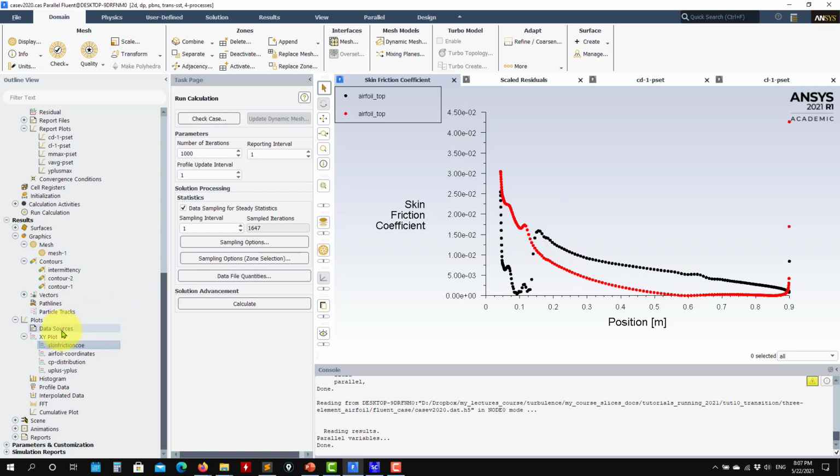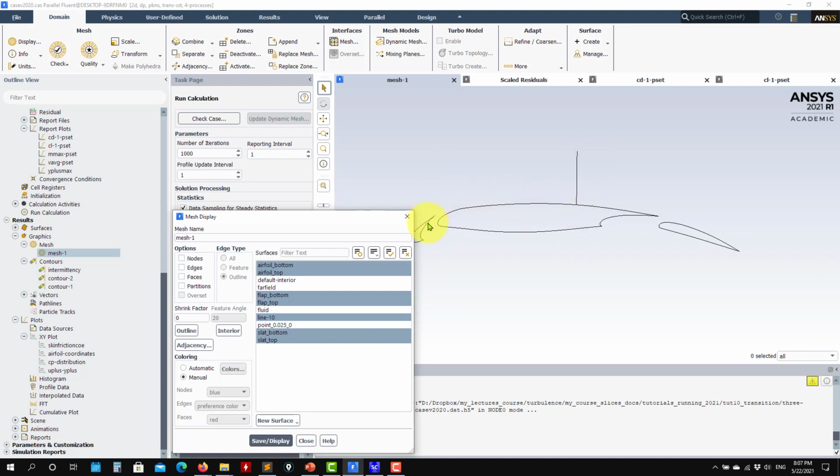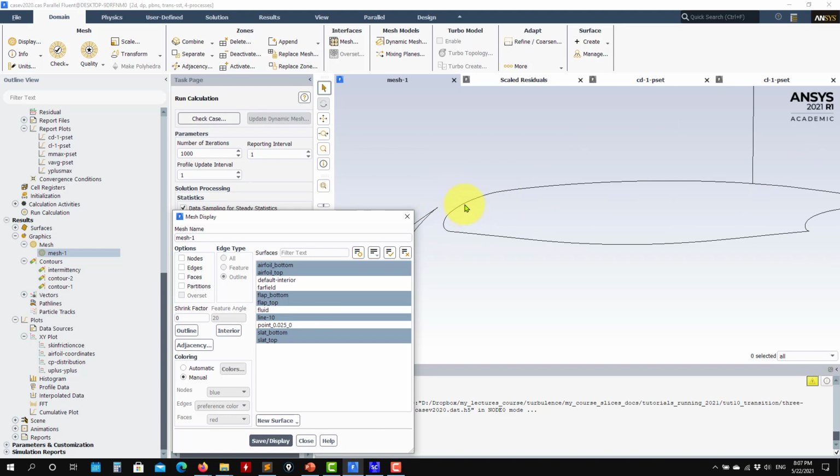Okay, so the final part that I want to show you here is the plot of the Y plus. I'm plotting here, I chose this point as a random point because I like it, but you can put whatever you want. Interestingly, you can probably do the same plotting where the flow is laminar, and you should get the solution that we know, but you should get the fit into the viscous law, not the log law that we're going to get here, where we know the flow is fully turbulent.